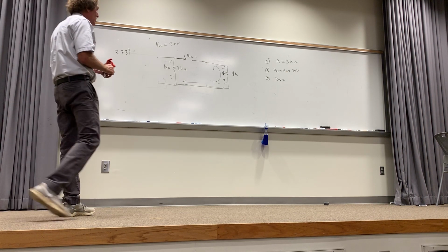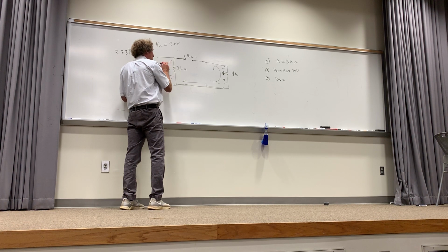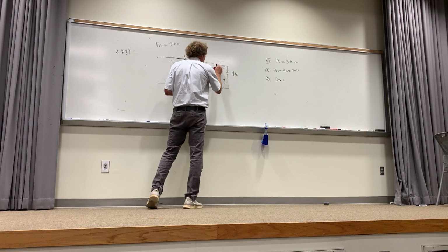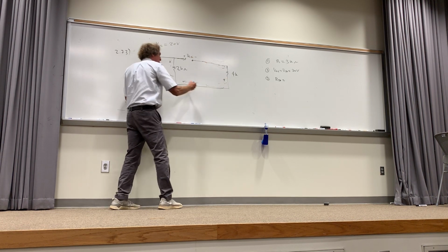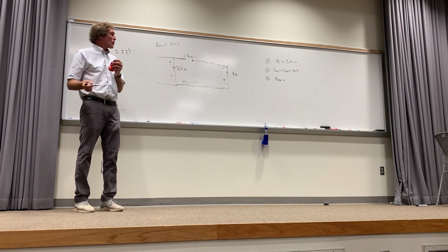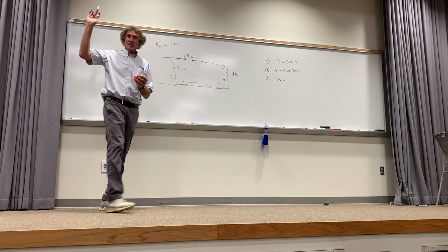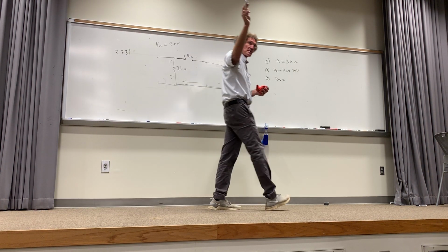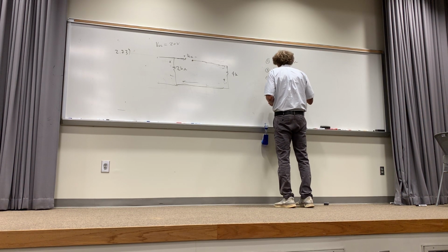Now, here, what is the resistance between these two? You can forget that 8 volts now on that one. Well, just start at one terminal. You all see these two are in series? It's just 4 and 2, isn't it, K? Or 6K. How many see that? It's 6K. You all see this, class? 6K, got it? It's 6K ohms. Right? They're in series.